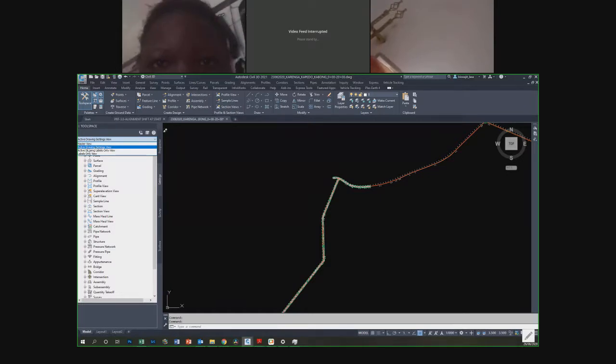One is the active drawing settings. This means whatever you change in the Settings area, if this one is selected, it will change only in this particular drawing, not in your Civil 3D template or the generic file which you get whenever you open Civil 3D.